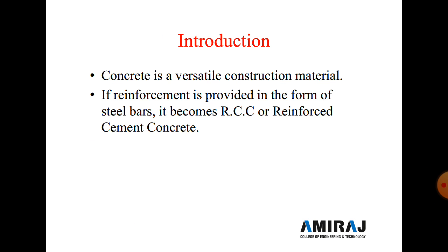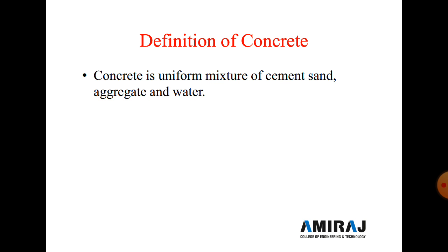If reinforcement is provided in the form of steel bars, it becomes RCC, meaning reinforced cement concrete, and if reinforcement is not provided, it is PCC, meaning plain cement concrete. Generally, in the construction industry, more than 70% of construction is RCC work.